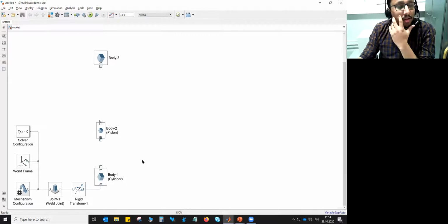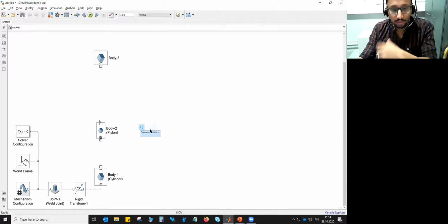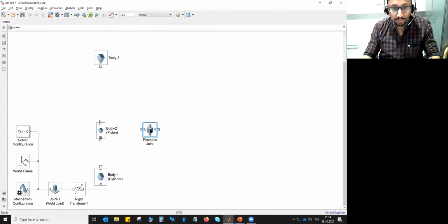Okay. Now we need a prismatic joint between body 1 and body 2. So let's search for prismatic joint. Let's rename it as joint 2. It's a prismatic joint.